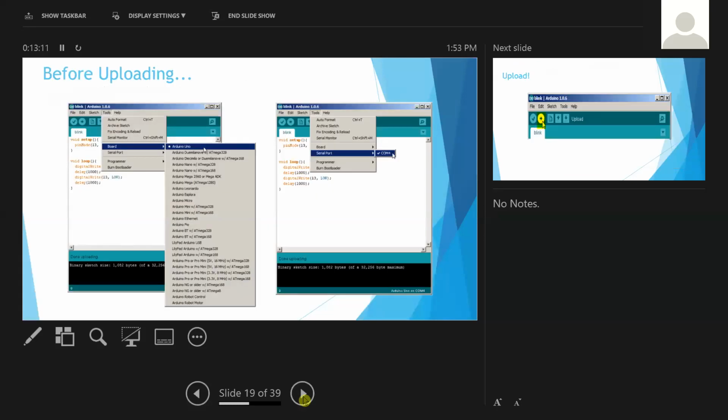Before you upload, when you're in your IDE and you have your Arduino connected to your computer, you need to go up to the top where your Tools menu is, go down to Board and over to the right, and make sure you're set up for the Arduino Uno. Also on the Tools menu, you need to check your serial port.